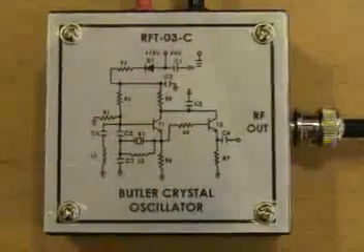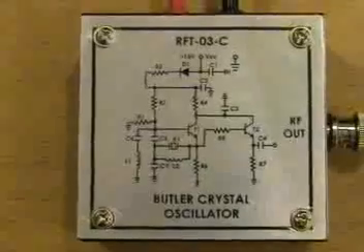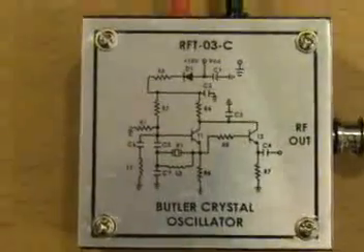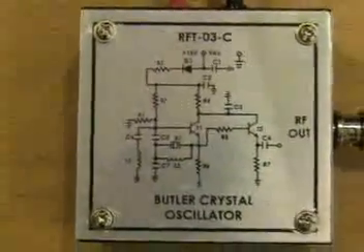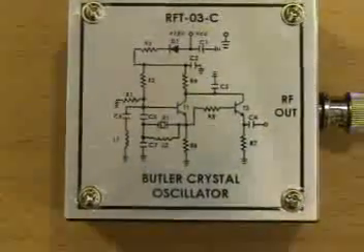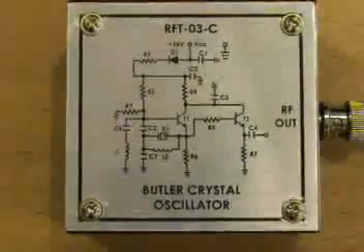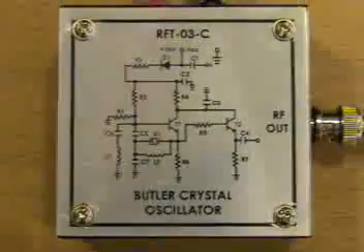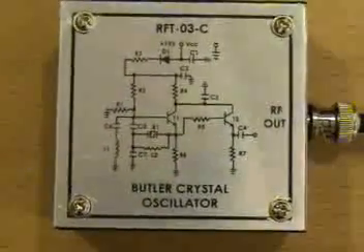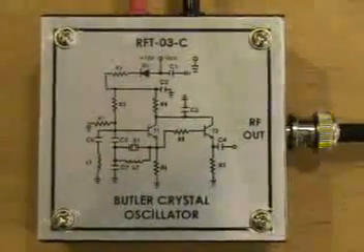So we are able to use higher frequencies for the crystal oscillators. Normally crystals are not available in the fundamental mode for more than about 20 MHz. If we have to use the crystal at a higher frequency, we have to use overtone modes for the crystal, and we have to use Butler crystal oscillator in that case.